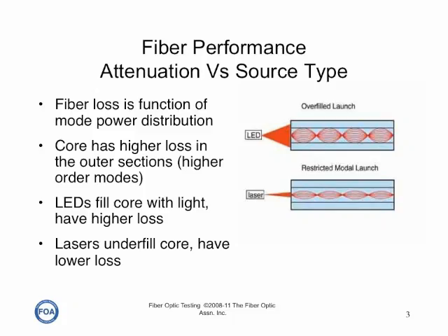The modes carried in a graded index multimode fiber are dependent on the type of source that you use. For example, if you use a broad beam LED, you may put light in most of the modes in the core. But if you use a narrow, restricted launch, like a laser, even something as straightforward as a VCSEL, which is becoming more common now in fiber optics, you don't launch much light into the higher order modes.